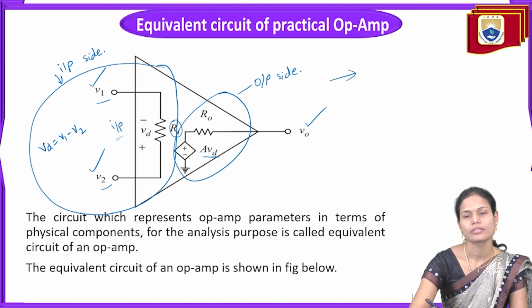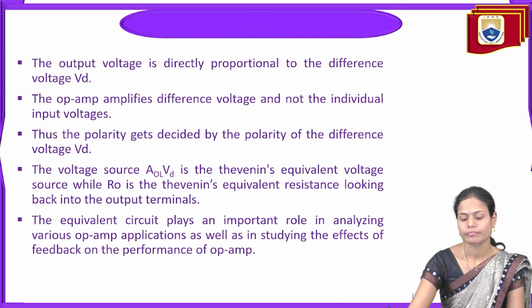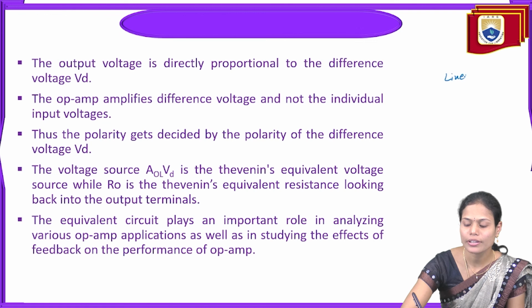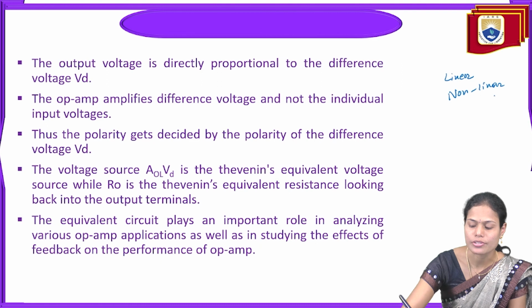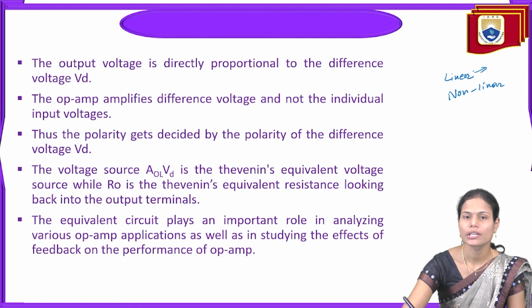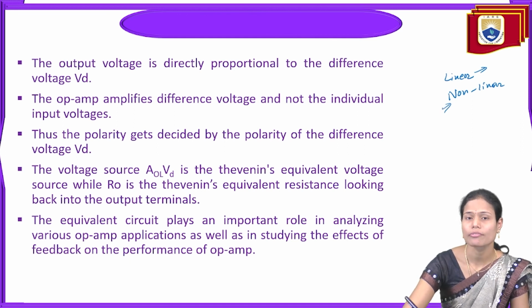In the case of this operational amplifier, it can run linear applications as well as non-linear applications. In the case of linear applications, we provide the feedback from the output to the inverting terminal of the operational amplifier. By using this, we can design the voltage follower, adder, subtractor, integrator as well as differentiator here.